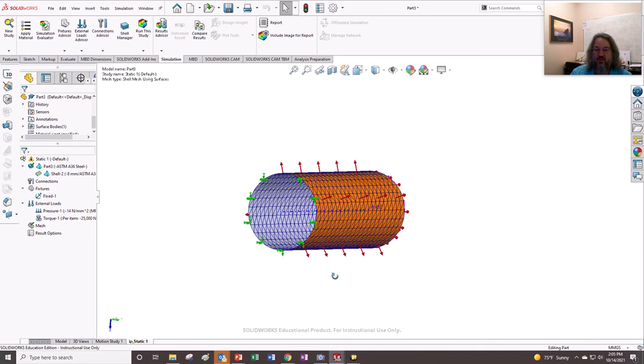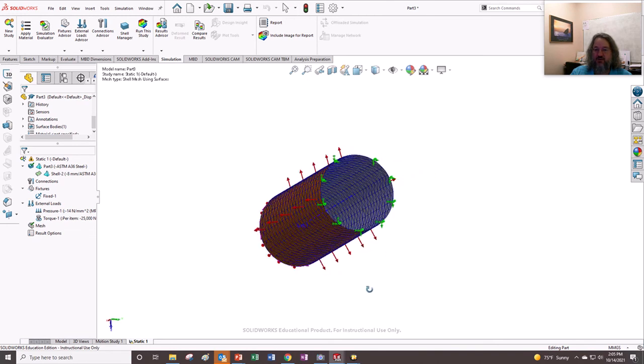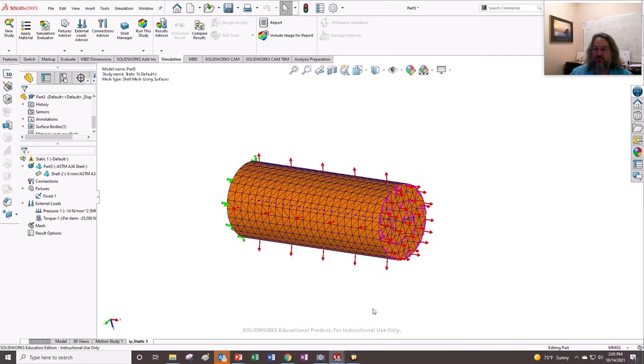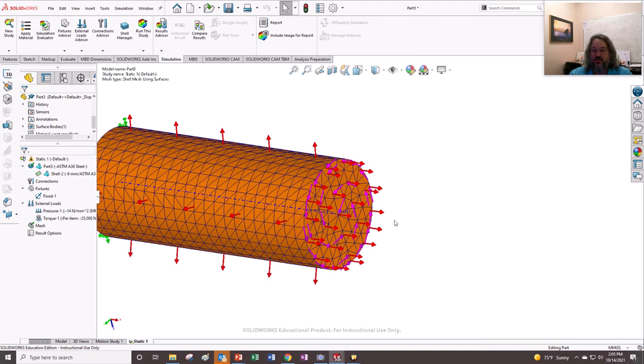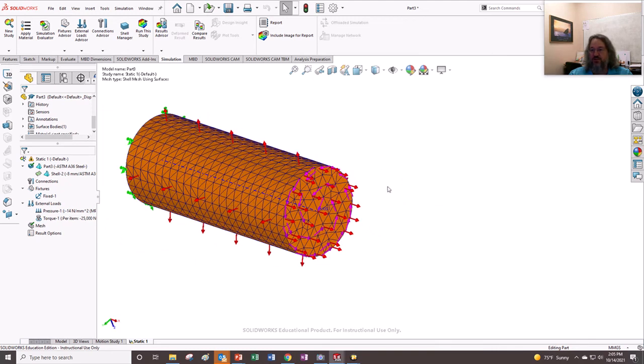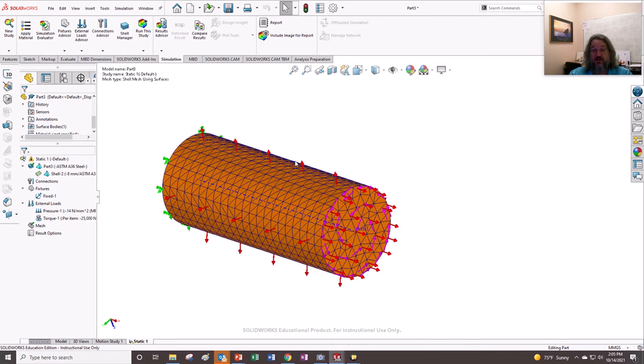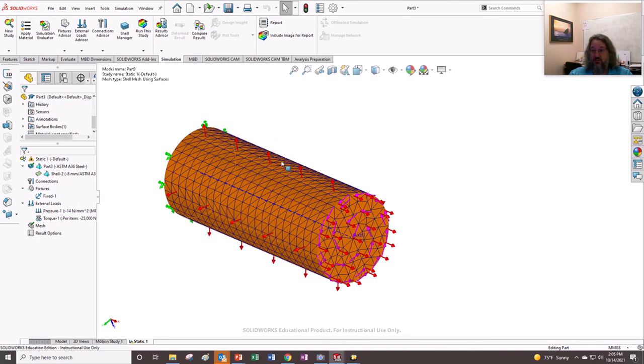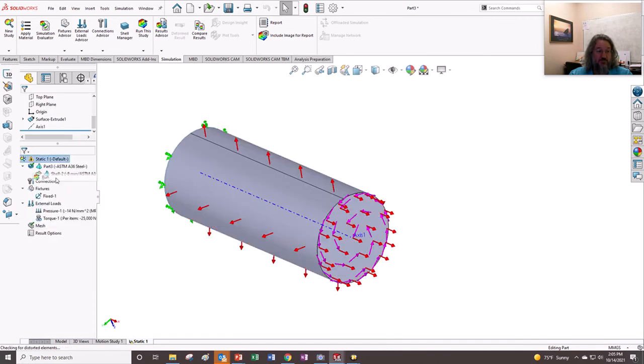Right. One thing that's important if you're going to use surfaces, the gray and the orange, and you have multiple things that are attached to each other, you've got to pay attention to the gray and the orange so that they don't flip things around. The orange needs to match with the orange and that kind of thing. There are always going to be issues where the plates join, so you've got to be aware of that. But this is your introduction to plate elements. Because you have a surface in SolidWorks, you can use plate elements in SolidWorks simulation, and we can run it.